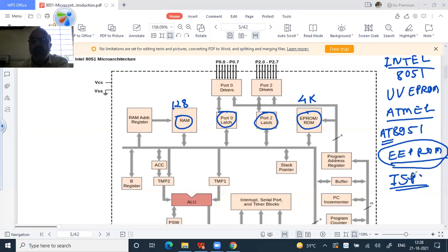You can program the chip within its application. A few pins are provided for programming purposes, and you have to connect the USB pin connector to that particular microcontroller card, where the programming pins have been brought out on the pin connectors.